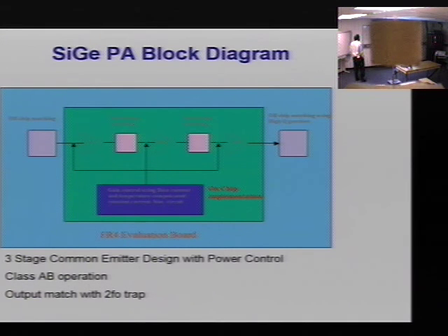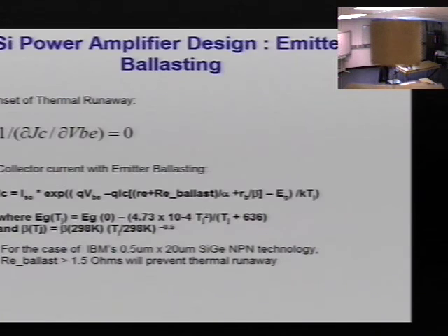Shaping of the waveform is very critical in the power amplifier, and having a lot of second harmonics would really cause unnecessary peaking of the fundamental waveform, and as a result, it causes a lot of efficiency hits, so you add an external trap to get rid of that.